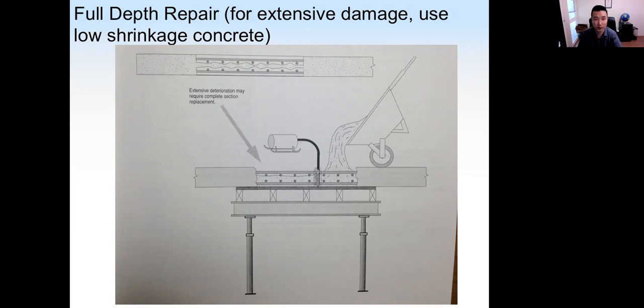Make sure to use low shrinkage concrete, otherwise we may have debonding due to a higher drying shrinkage of the repair materials.